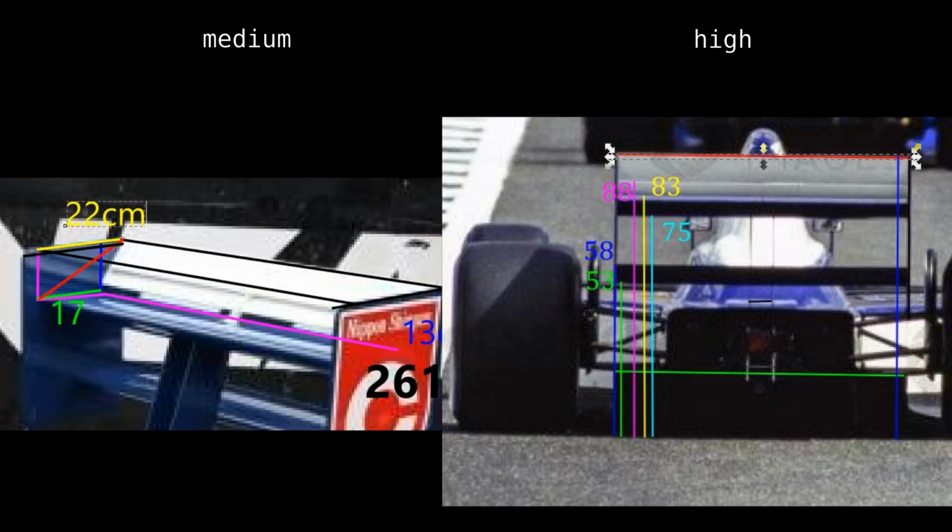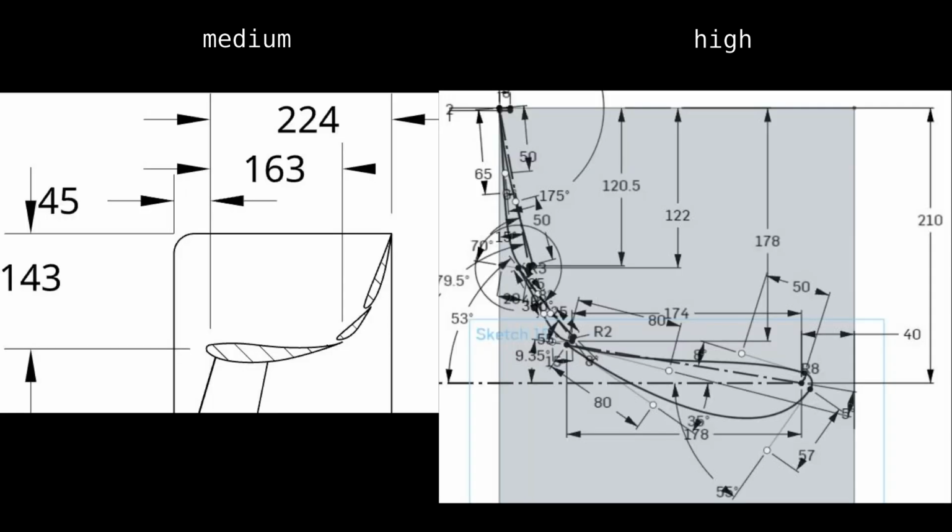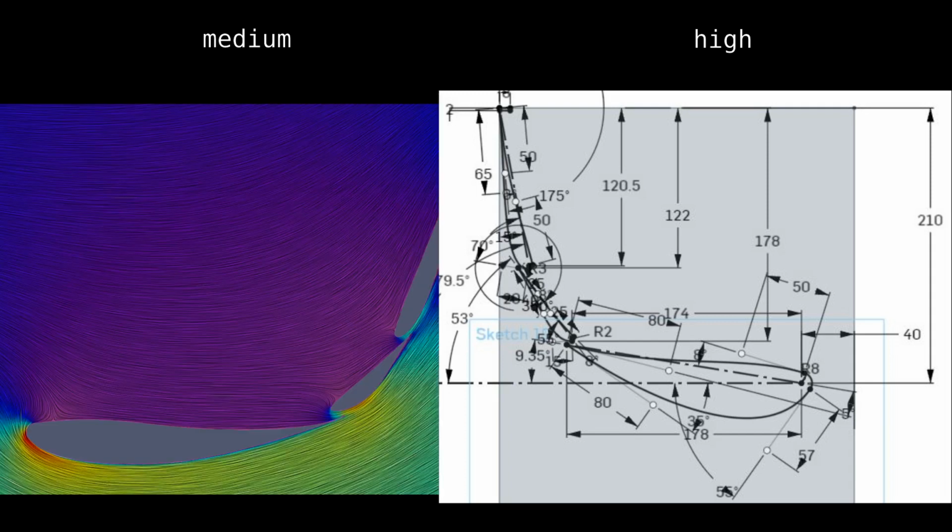Now I have some numbers to aim for, and I can make aerodynamic sense of the dimensions derived from the images available. For this car there were 3 distinct setups: low, medium and high downforce. Here I'm trying to replicate the medium and high downforce wings, with an emphasis on the high downforce wing. The size difference relates to the depth of the first element, with the medium being about 150mm and the high being about 230mm, with a gurney flap.